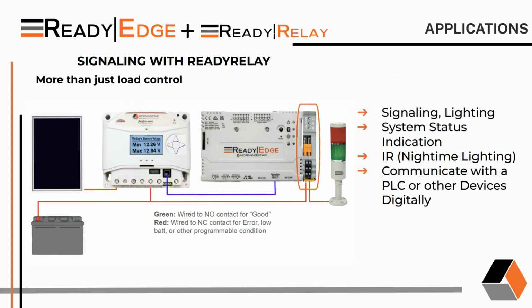So again, that could be the PLC we were just talking about, or maybe lights on the top of the box. I could see the DOTs that we work with putting a couple indicator lights on the top of their box, red and green. If the battery's low or if there's an error in the system, then you get a red light. If nothing's wrong and the battery's good, then you get a green light. So as you're driving past these things on the highway or wherever they may be, you have a quick glance to see, and you might find that that's a better way.